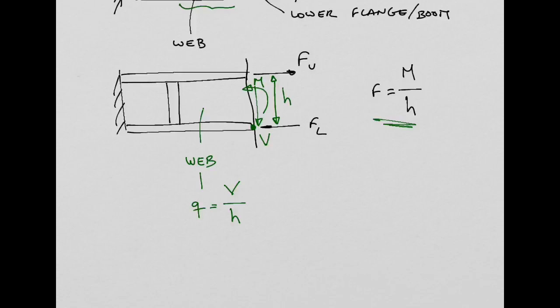Yeah, so if you want to get the shear stress, you just need to divide this shear flow by the thickness of the web, of this plate. Then you get the shear stress. And if this thickness is large enough, the design criterion is, for example, if you use the Tresca yield criterion, right?